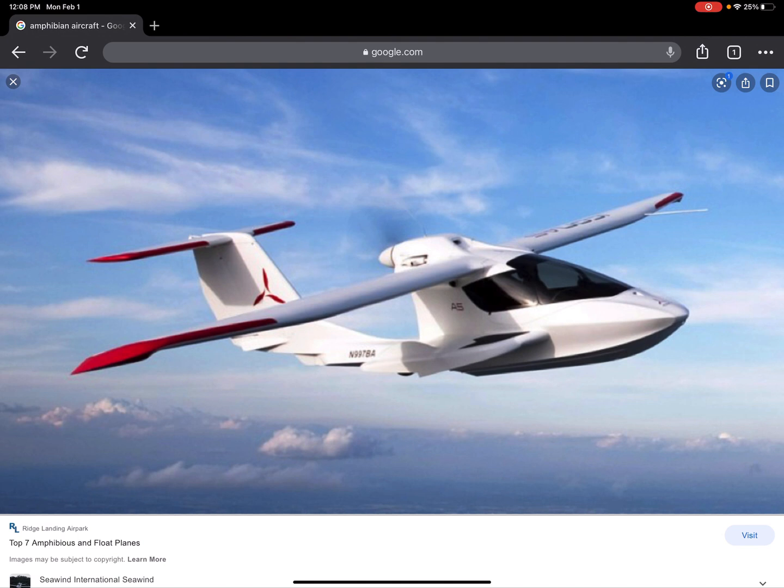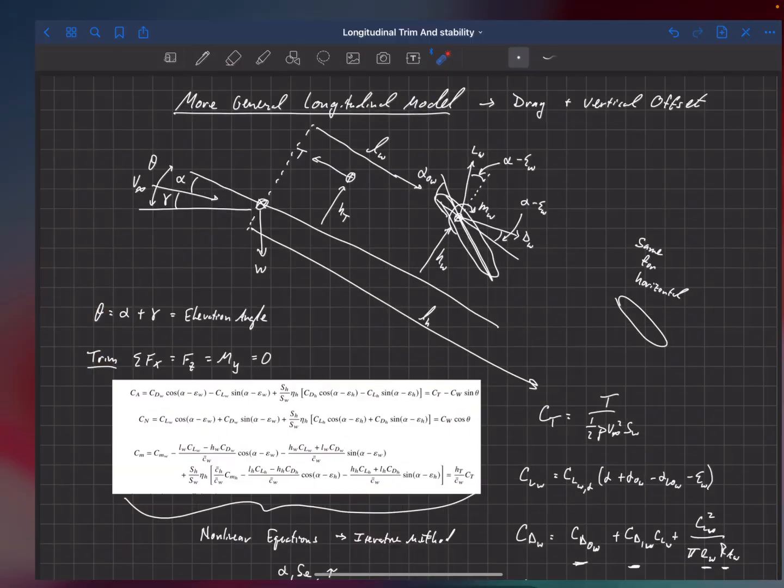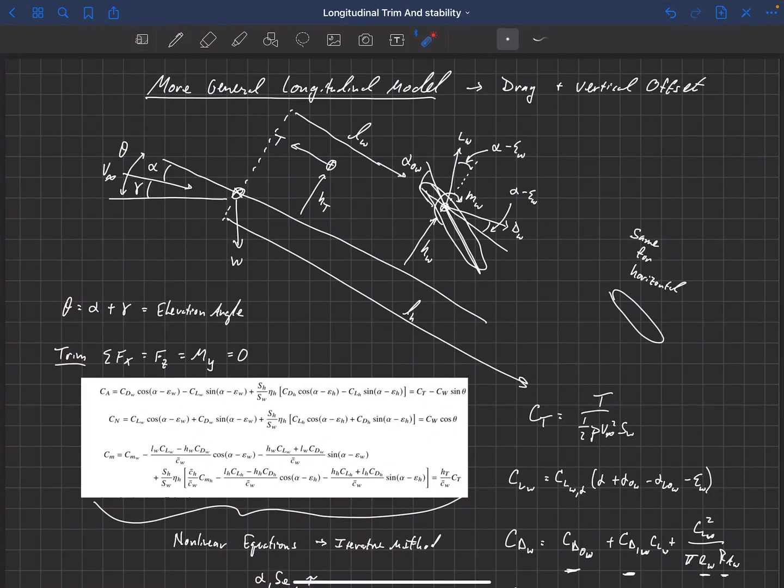And so that propeller often is sitting a ways above the center of gravity. And as you flip through these different pictures here, you can see that that's kind of the trend. So let's talk about what that means. During takeoff, this is especially important, because we've got thrust here that's vertically offset from our center of gravity, and we're at somewhere near full power, so we've got a lot of thrust. That means we have a very large nose down pitching moment here due to the thrust.